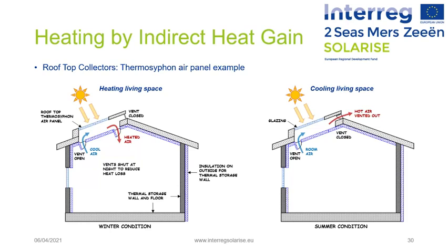It is essentially an absorbing surface with minimum thermal inertia and a glazing over it, thus forming a solar air heater. It absorbs incident solar radiation and heats up the air in the absorber glazing space. The hot air forces itself into the living space through the vents and warms it up. Cooler air takes its place and the cycle is repeated.